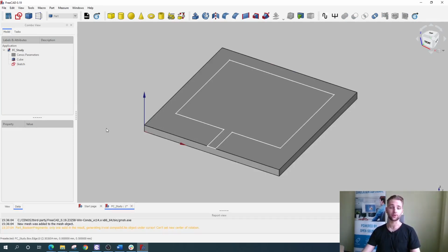By default, FreeCAD is necessary only for the geometry building, as the numerical mesh for your antenna is generated automatically when you calculate your simulation. However, in some cases, the automatic meshing might fail, and in such occasions, you will need to create your mesh manually. For this reason, let's take a look at how to mesh a very simple patch antenna manually.